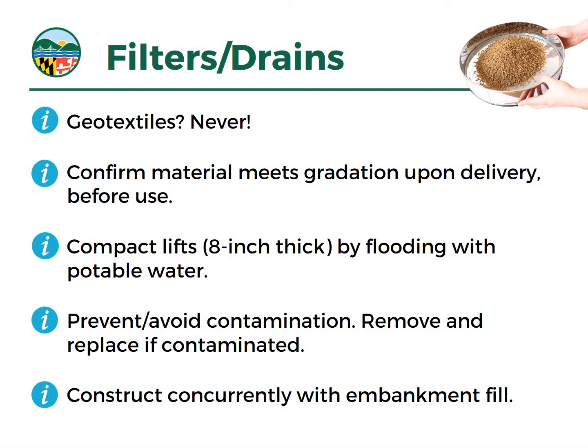All right, moving forward to internal filters and drains. I'm going to say this a couple times, but should we use geotextiles? No. Should not be using geotextiles. This is national practice on the federal level for over 30 years now. Basically any major dam organization on the federal level, Army Corps, Reclamation, NRCS, strongly advises against geotextiles in any area where their use is critical for the function of the dam.